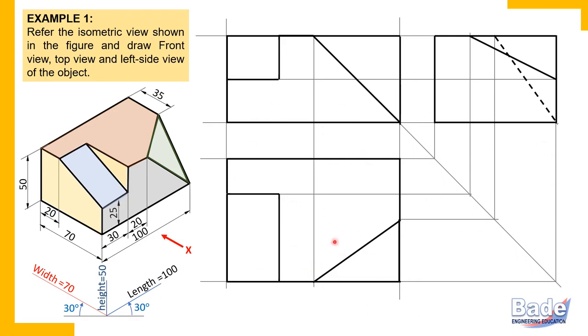Now listen, after completing the drawing, you should insert dimensions. All given dimensions are to be inserted. Remember, as far as possible, don't insert dimensions inside the views. Smaller dimensions must be nearer to the boundary. And boundary and dimension line, that distance must be at least 8 millimeters. Of course, you need not measure that 7 or 8 millimeters. It means just sufficient distance from the boundary.